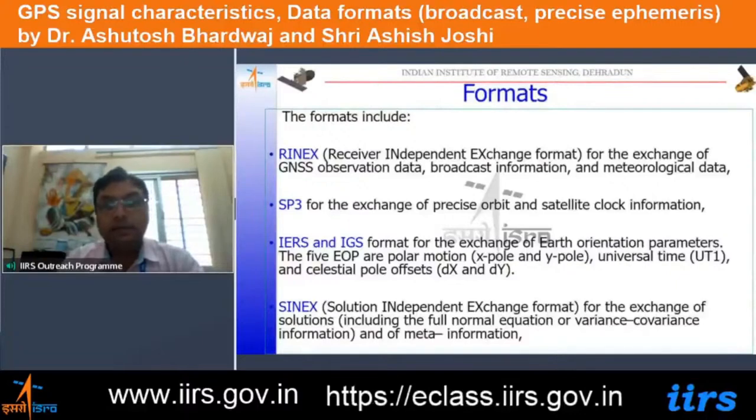Now, in the standard procedures with the commercial softwares, we require much less effort. We normally import the rover data and the base station data, and we directly process it, either with the native format or with the RINEX format. But for some high-end processing, other formats are also available, and we can download the IGS station datasets also, either as SP3 files.